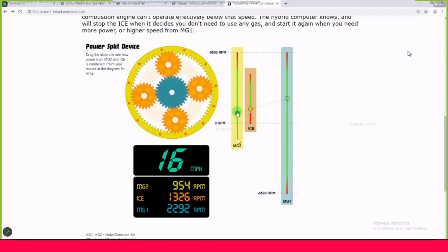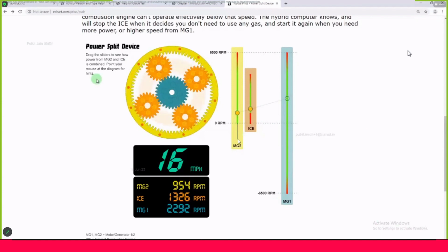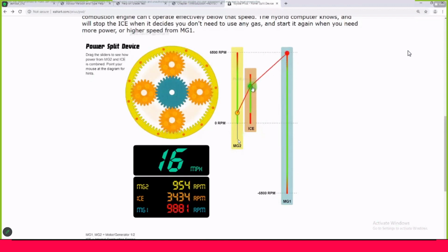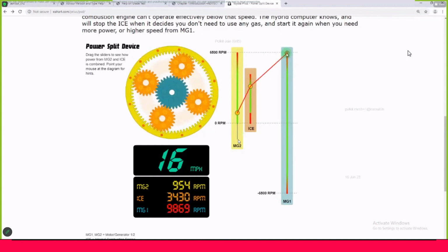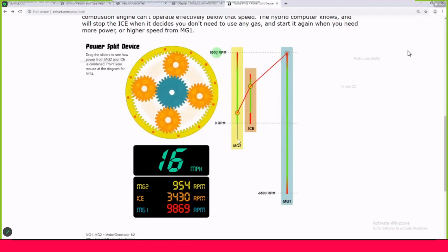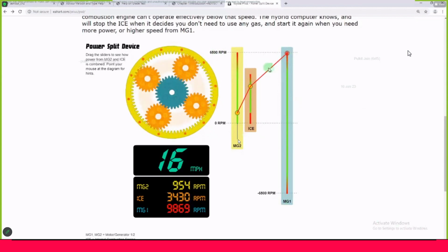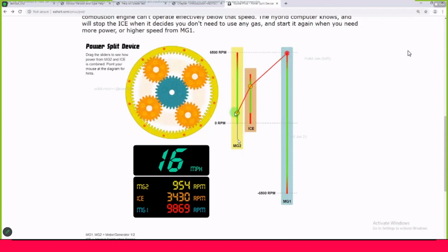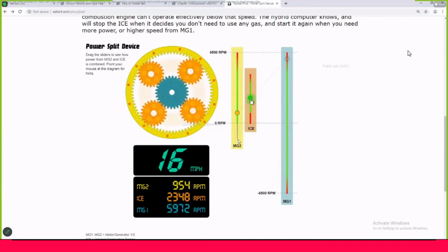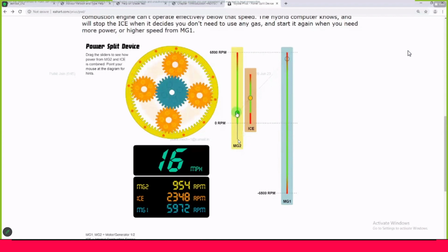So this happens through a typical power split device inside a Toyota Prius. So here you can see, if I increase the engine RPM, the engine is going to share the load, and I cannot go beyond a typical value. Here I am going to see one alarm where the maximum RPM for motor generator 1 is limited to 6500, and now this is no longer in line. So for a safer value, or for possible values, all these 3 points should be within a line.